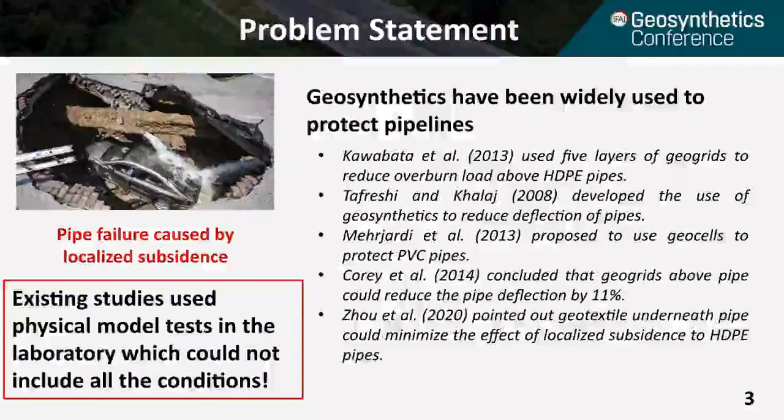And then Joe, basically my student and the co-author of this paper, and I did research where we put the geotextile underneath the pipe, and in the physical modeling in the laboratory, we found out the geotextile can really minimize the effect of localized subsidence on the HDPE pipes.